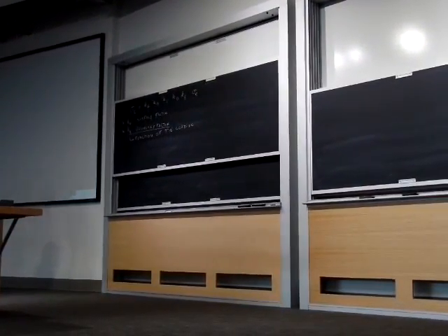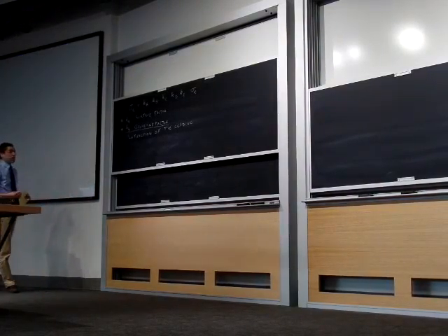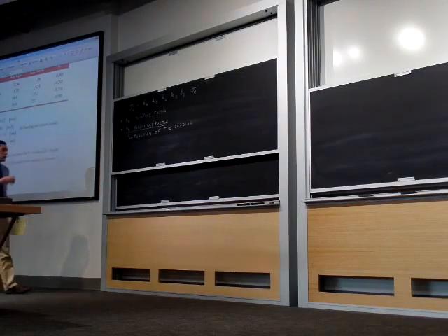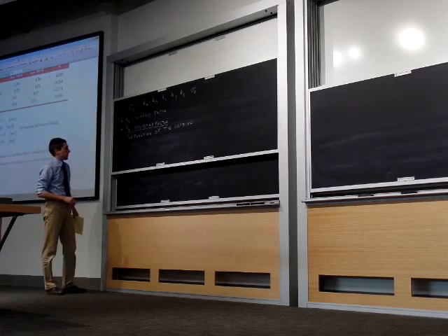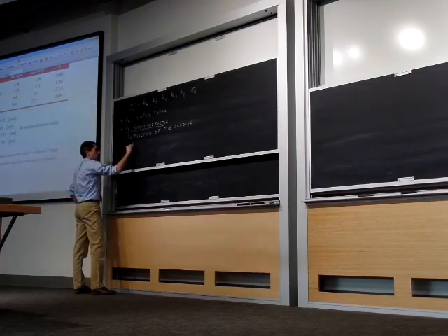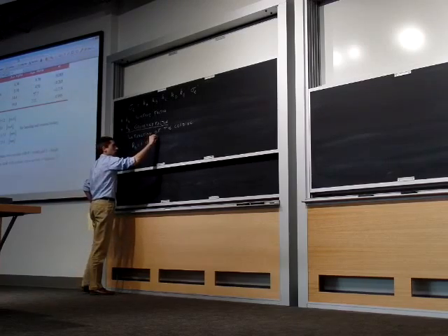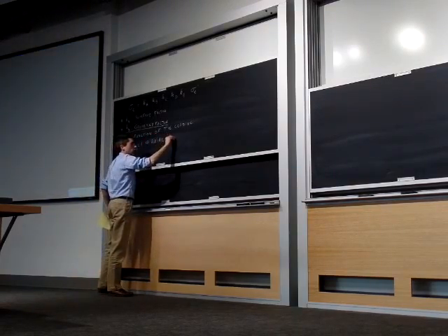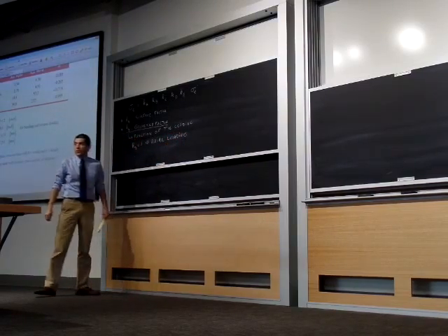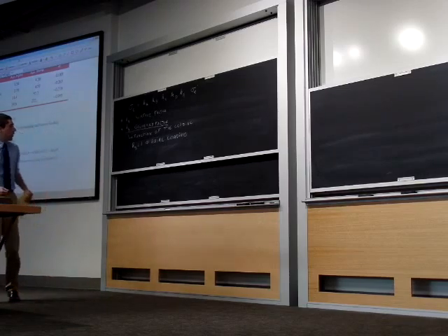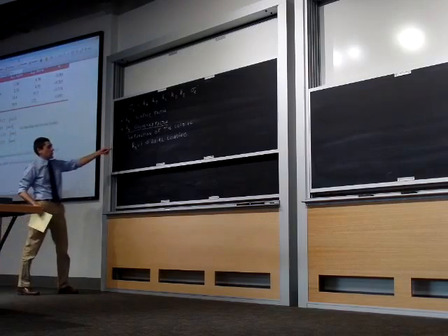So there isn't necessarily any physical reasoning for that other than that experiments were conducted, and based on those experiments, conclusions were drawn, and they're cast in this form of endurance limit modifying factors. And so we say that Kb is equal to 1 if there's axial loading. So if there's axial loading, it doesn't matter that our mechanical element is different from the Moore specimen. Our endurance limit is not going to be affected by that because Kb is going to be set equal to 1.